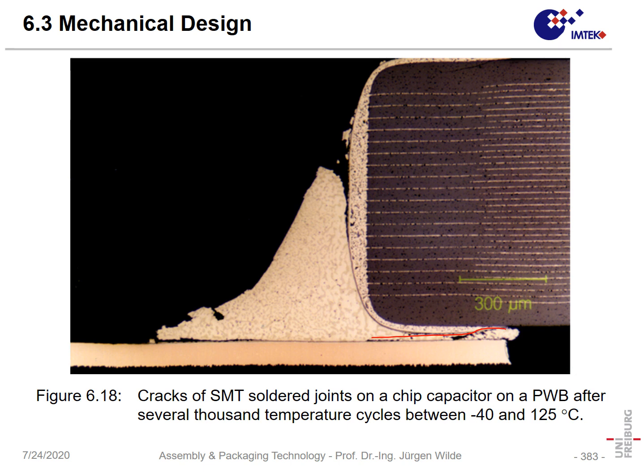For instance, here on the surface of that device, we can see the area that is affected by shear is around here. That can be clearly seen from that larger grain size. So that's a good indicator. When such a sample has large grains inside, in some locations, that's an indicator of large strain. Again, we can also see here are areas of large strain around here.